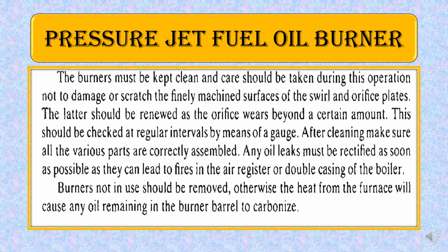These burners must be kept clean when we talk about the maintenance part of it, and care must be taken during this operation not to damage or scratch the finely machined surface of the swirl and orifice plate. When we are doing the maintenance, we have to be very careful that no scratch is created on the orifice plate as well as the swirl plates, because these are very finely machined parts and any damage is going to change the throughput. Suppose you are cleaning the hole of the orifice and it is enlarged; generally it is not, but you have to take care of it.